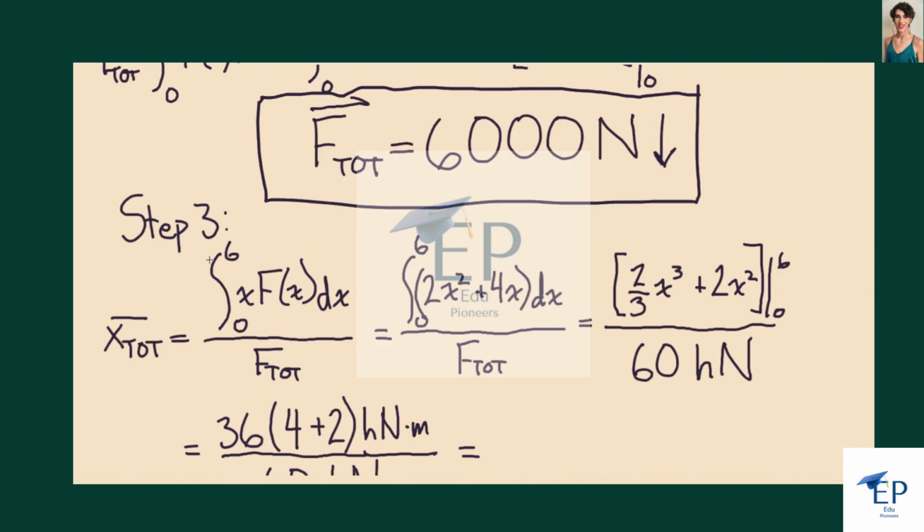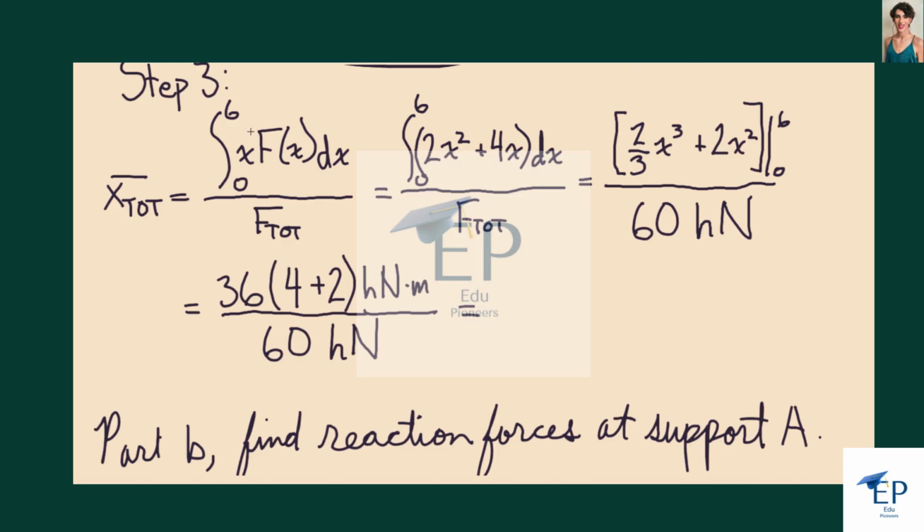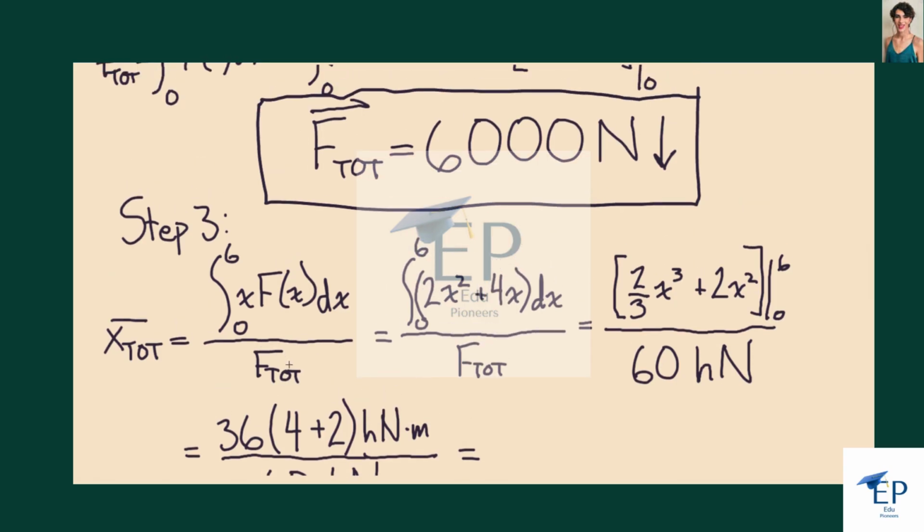I'm sorry, in step 3. To find the centroid, we will use that force load density function that we defined, but this time we're going to integrate it by the product of x over the span of dx. So this is going to turn out to be a different integral in the numerator. Our denominator is simply the total load, which we determined in the previous step, step 2.